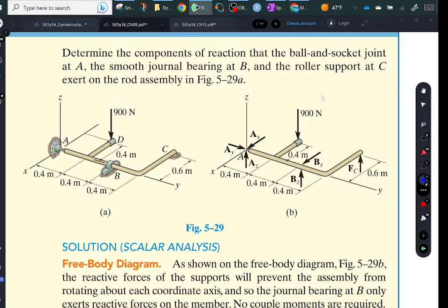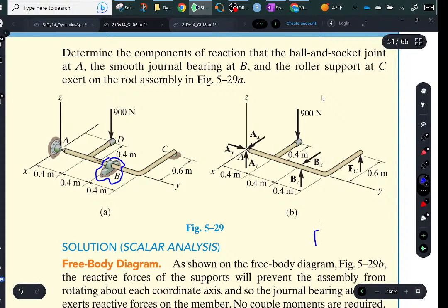So you just need to be aware of that when you're looking at these in the field, that you need to ask the question, really, if I put a bearing in there, if that bearing is really thin, I don't know the definition of thin, but say a thin piece like this and the rod goes through here and that rod could move in that bearing kind of freely.